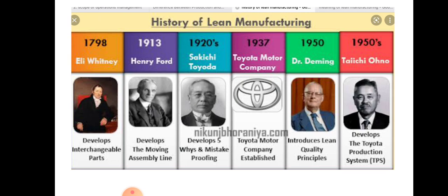And the seventh principle is use visual control so no problems are hidden. That means the company should use simple visual indicators to help people determine immediately whether they are in a standard condition or deviating from it. They need to avoid screens from the computer when it moves the workers' focus away from the workplace. So they need to design a simple visual system right in place where the support should be, then reduce the reports to one piece of paper whenever possible, even for important financial decisions.